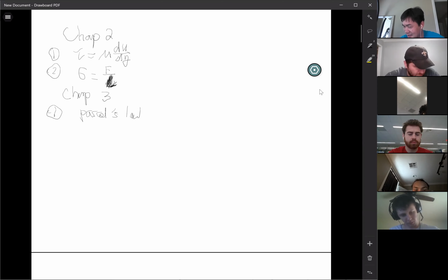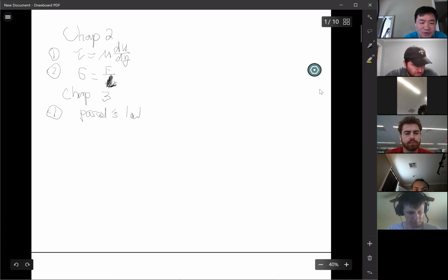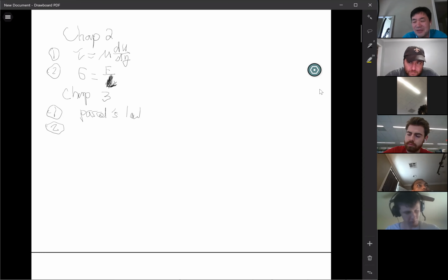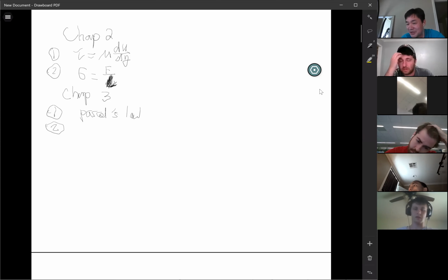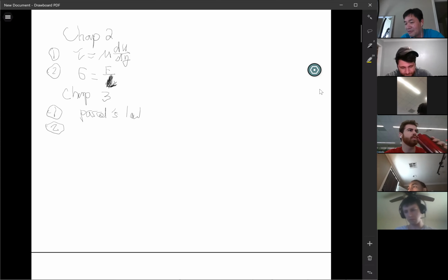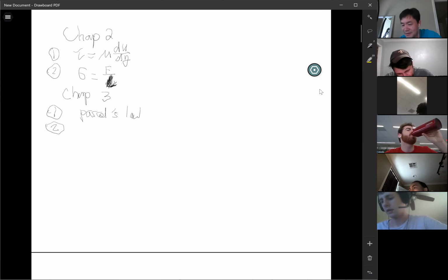We had classic examples, remember? I have homework problems, but I do have one example, a hydraulic jack, to make force. So Pascal's law, what is the equation? The equation is easy: delta P equals delta P. The added pressure is the same everywhere. Not much of an equation. But I think really the equation is force equals pressure times area. That matters. You have added pressure, and you have to have an area to convert the pressure into force. Does that make sense, everybody?